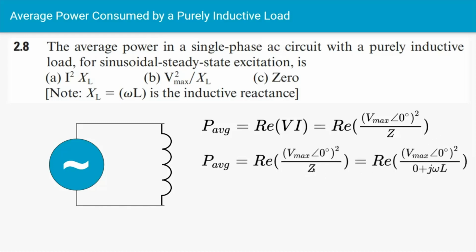So let's go a little bit further with that. Let's remind ourselves that the impedance in this circuit has no real part to it. There's no resistive part to it. So the first term is going to be 0. And then the reactive part is going to be omega times the inductance L. We get that from the inductive reactance, which is equal to omega times L, the inductance.